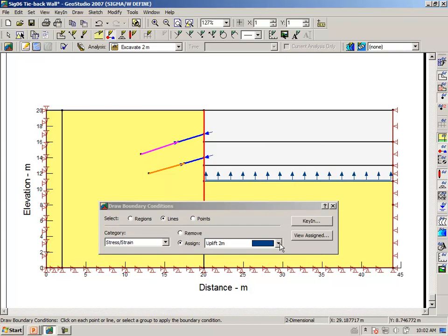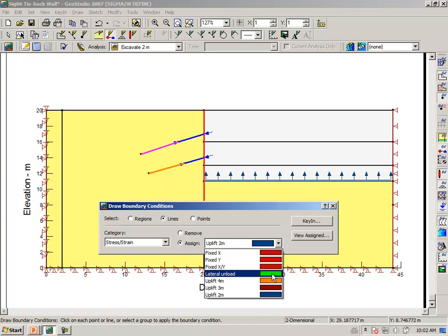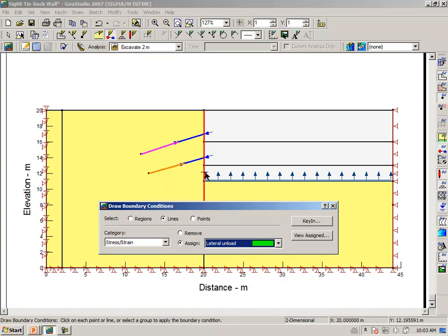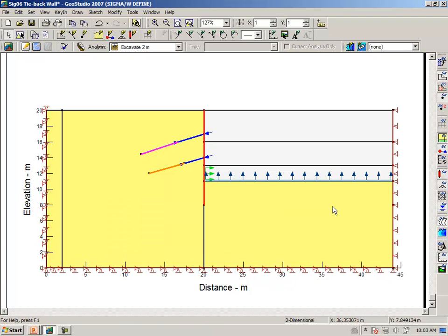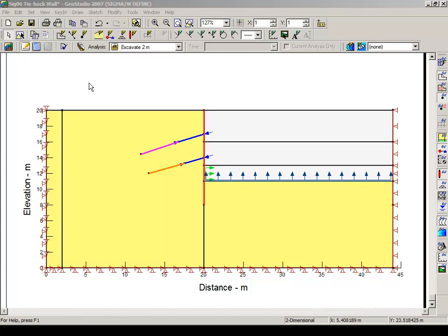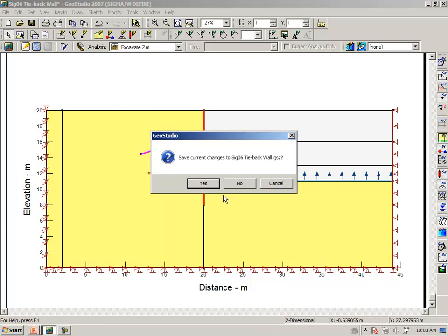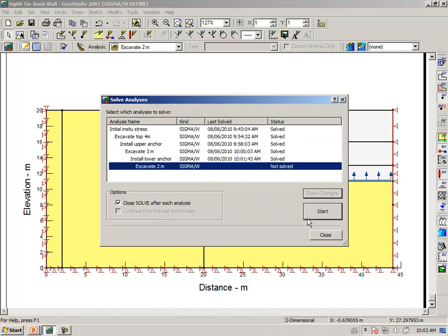And once again, we have to apply the lateral load representing the removal on the sheet pile wall. Recall that, to repeat once again, before we made any excavation, we had a stress distribution like that. So in this case, we are removing this amount of stress at this analysis stage. Solving then for the last analysis.